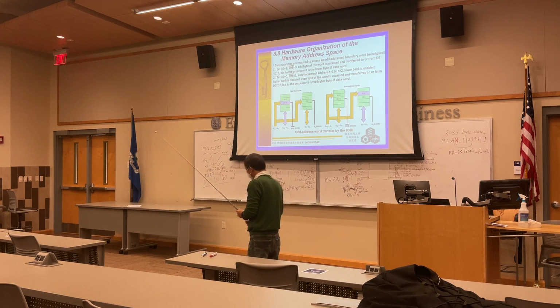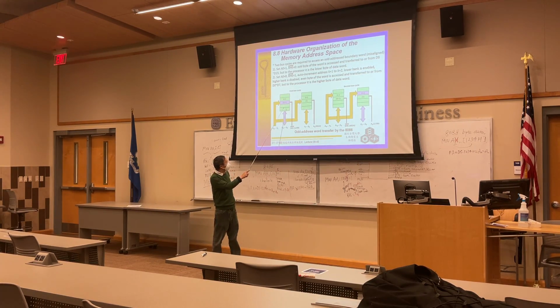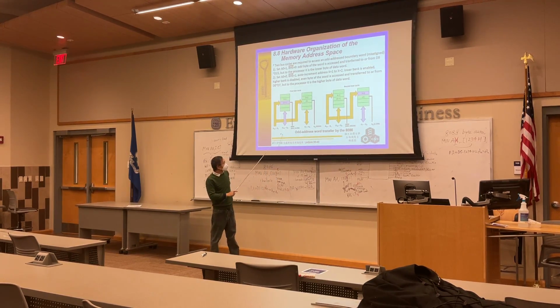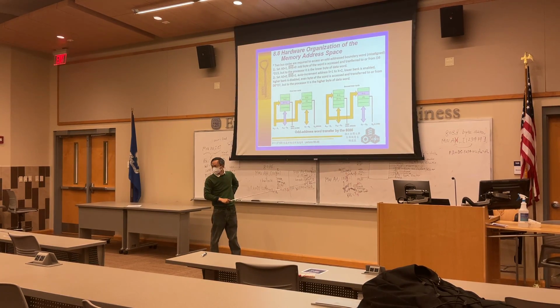Okay, how? We're going to do two steps. First step, we're talking about address 5, an odd address. A0 is 1, disable the lower byte, and BHE we set to 0 to enable the high byte. You broadcast the address and grab this high byte. This is actually the lower byte of your data, but you send it on the high byte of your data bus. But the microprocessor knows this is for the lower byte and sends it to AL.